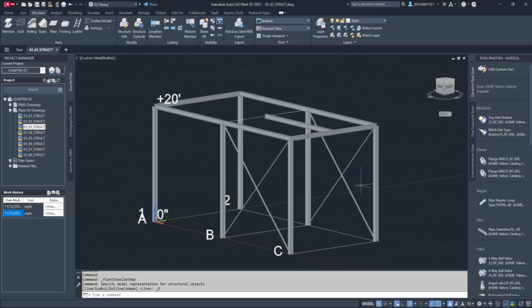Lastly, confirm layer settings and freeze the grid layer if needed, ensuring visibility is maintained throughout the design. Note that this setup provides basic intelligent shapes, which will later serve as a foundation for civil designers to complete the model's detailing.